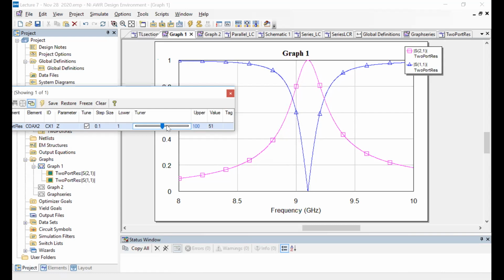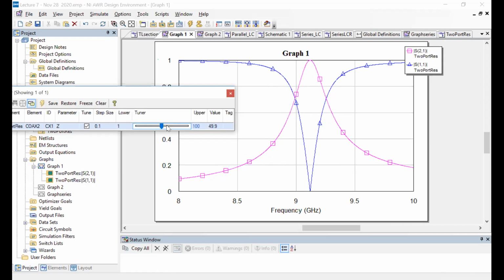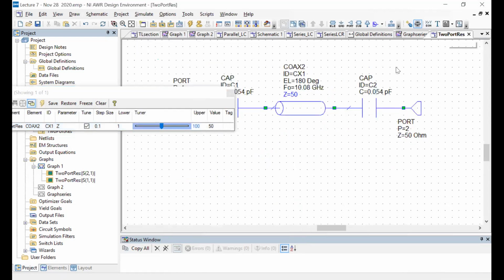So when I increase the characteristic impedance, I'm decreasing the capacitance of the resonator, and hence it has a bigger shift from its true frequency because of the coupling capacitor, and vice versa. Okay, yeah, so that's the argument here. Okay, good. So anyway, coming back to the main point we were discussing, this does not change the peak from 1.